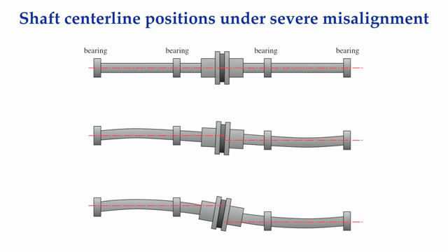If the shafts were perfectly balanced before they were misaligned, they are perfectly balanced now also. The center of mass at every point along the elastically curved shaft is still coincident with the center line of rotation at every point along the shaft. If we disengage the coupling in the extreme misalignment condition shown in the lower two shafts, each shaft would spring back to the dashed red lines which define the center line of the two bearings that support each shaft.